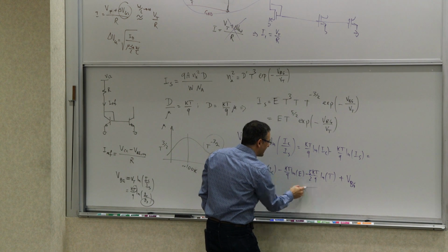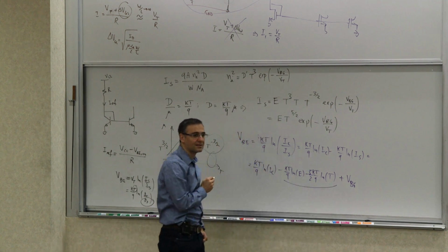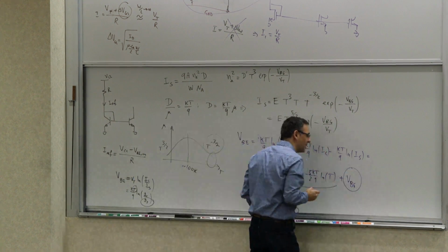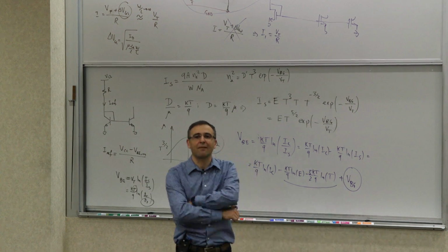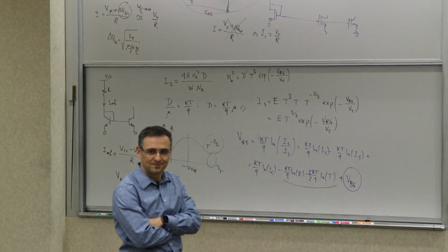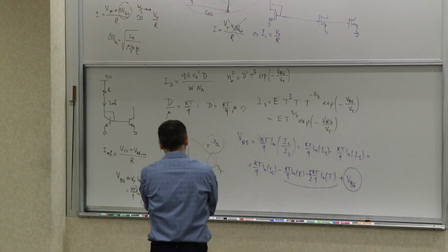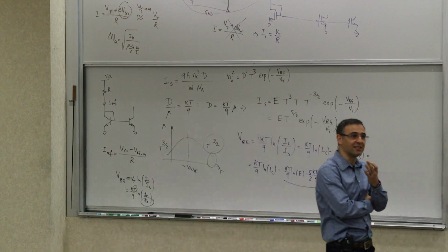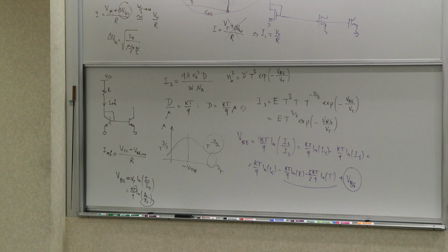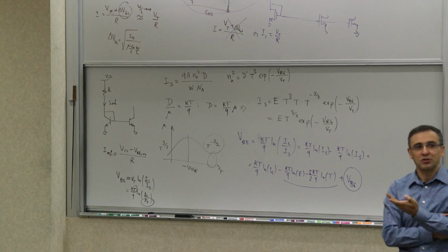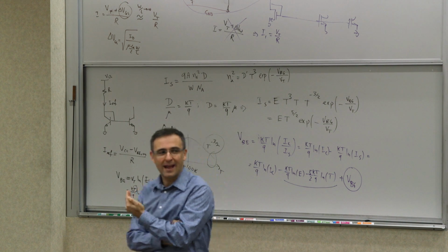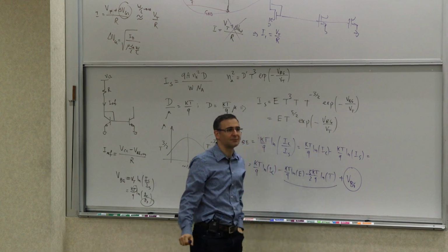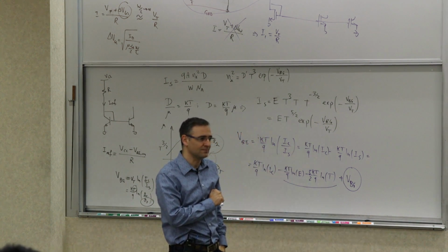So what you see here is the negative temperature coefficient dependence. And the other interesting thing that you see here is that it's directly related to the band gap voltage. Now, the band gap voltage of the semiconductor is an intrinsic property of the semiconductor. So you don't expect it to depend too much on the supply voltage or process variations or even temperature. And that's a good thing. So eventually, our target would be to get to this voltage and use that as a way of making a reference. Okay?